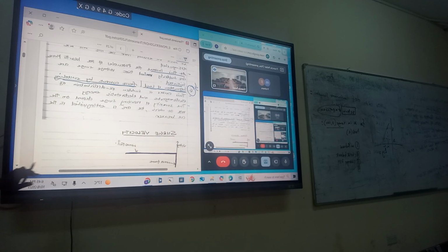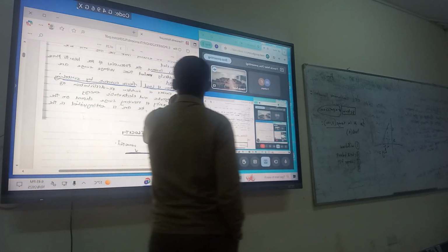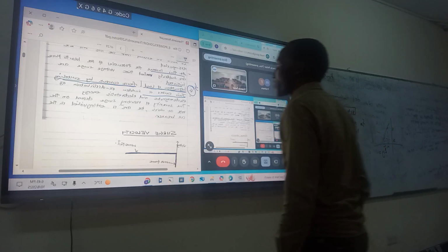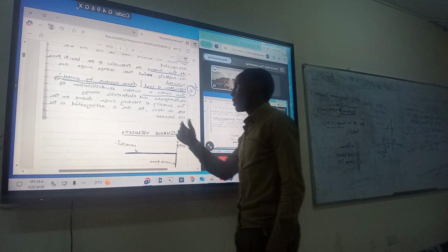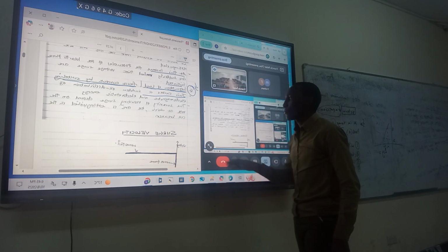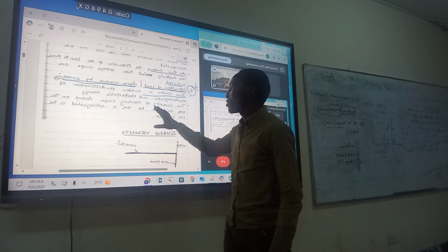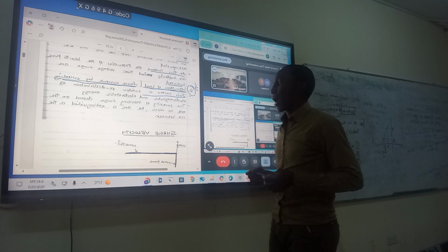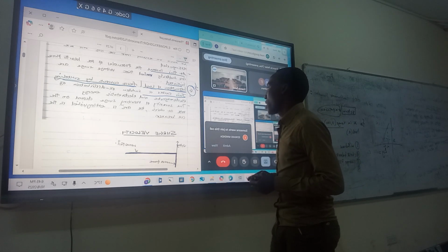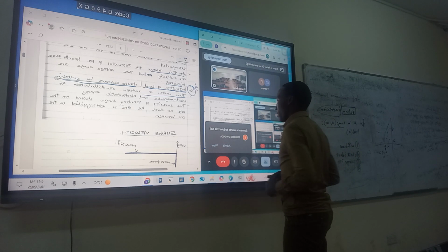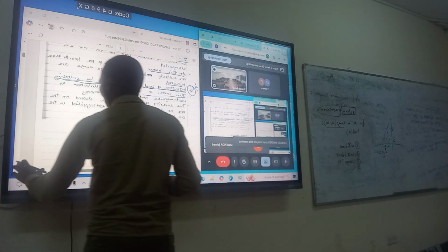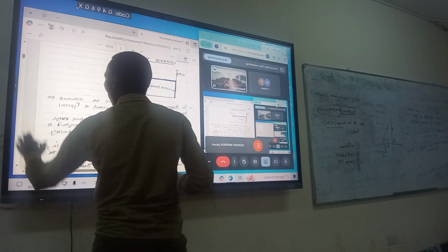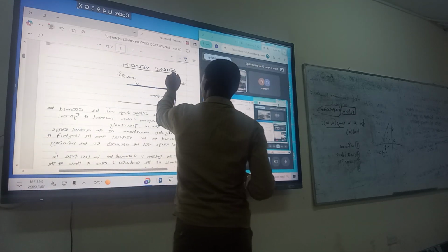That causes a sudden redistribution of the electromagnetic and electrostatic energy, whereby the severity of the resulting surge depends on the rate at which the arc is extinguished in the circuit breaker. Therefore I want us to check on the surge velocity.